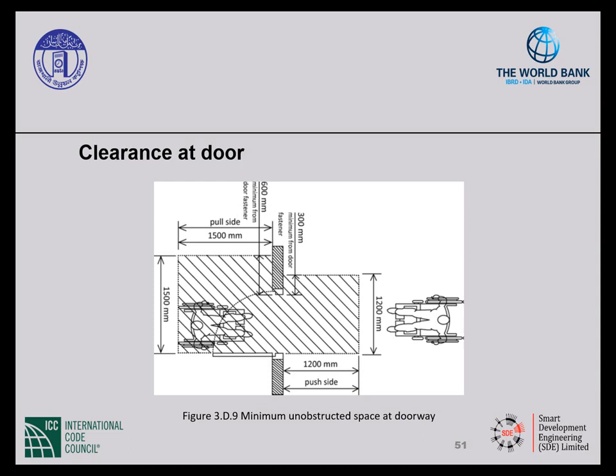Now, on the next slide, I'm going to show you a little bit more about why you need to provide these clearances, but I do want to point out, and it's easy to see on this slide, that as you're pulling the door away from you, that extra clearance would be for your foot plate, and as you're pushing the door towards you, that extra clearance beyond the edge of the door would be so that you could just slightly twist to be able to open the door handle.